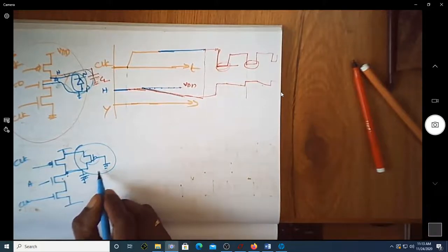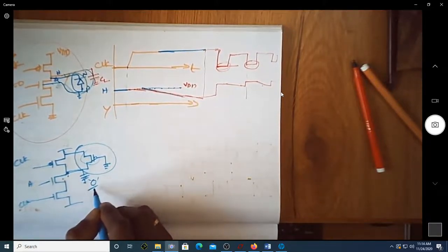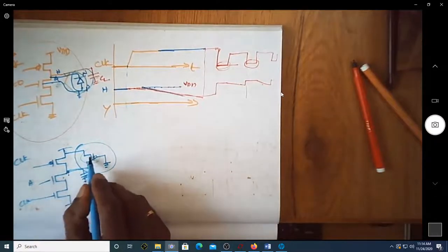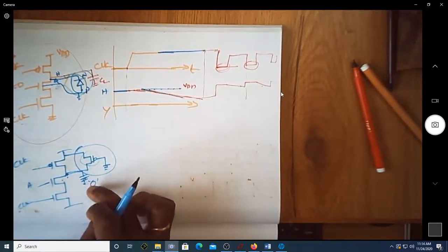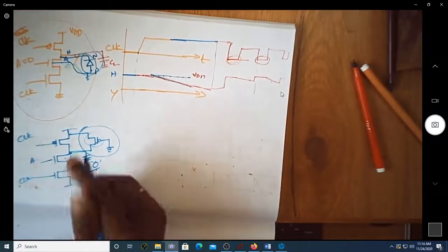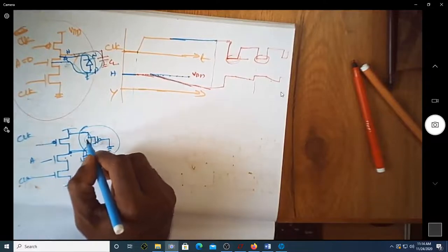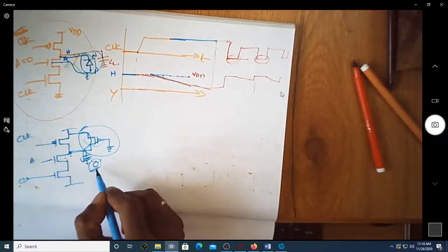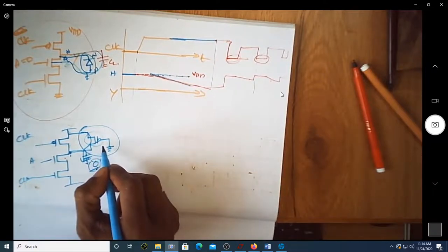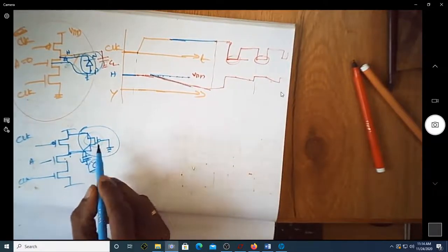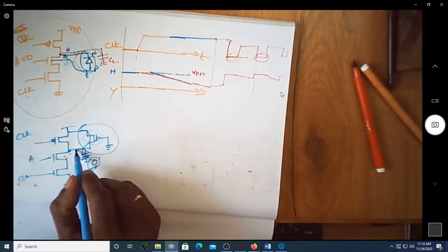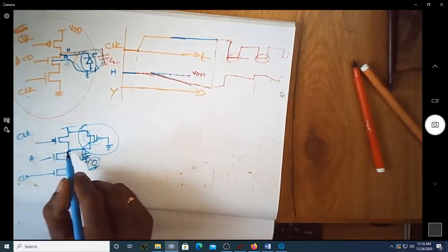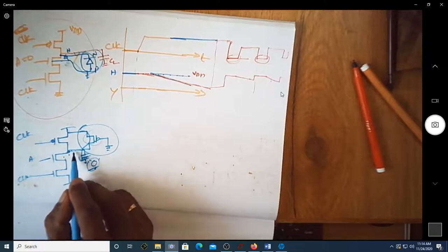Suppose the output voltage is 0. If the output voltage is 0, since you have this logic to overcome the charge leakage, this is always on, so whatever was 0 might get filled by this transistor which is on. So you may not get it as 0. Why you're not getting it as 0 is because this is always made on. So this type of transistor, which is used to keep the voltage at VDD when the output is supposed to be VDD, is good.